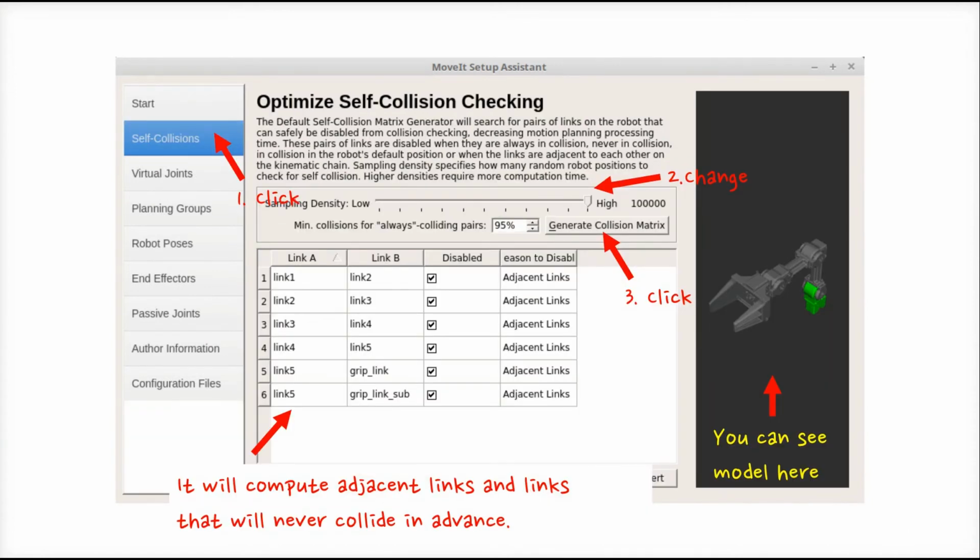This step is for checking the self-collision. As long as the simulation uses the rendered model, the overlap between two models will be self-collided. So the simulation should ignore those parts to avoid the collisions. And if you generate with high sampling density, the simulations afterward will avoid the self-collisions very well, despite the huge computation time. The links on the tables are the parts that can be self-collided.